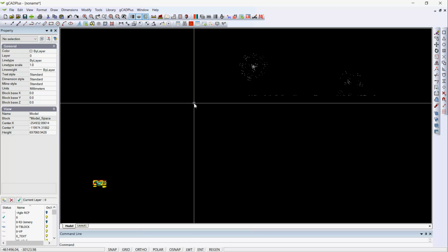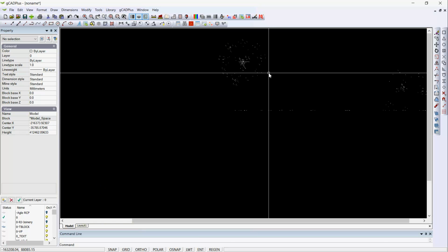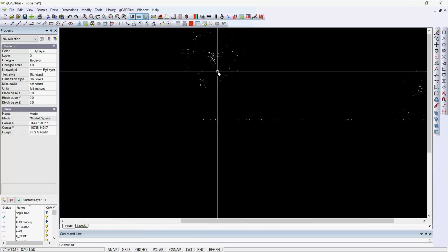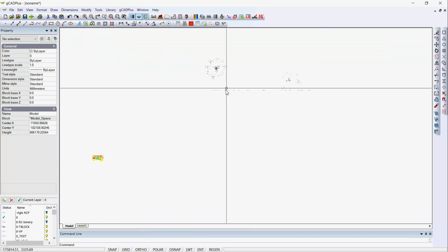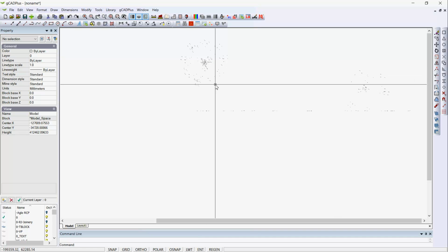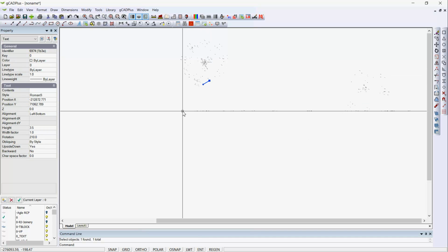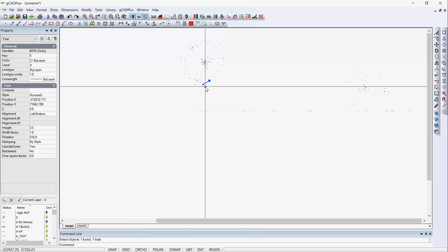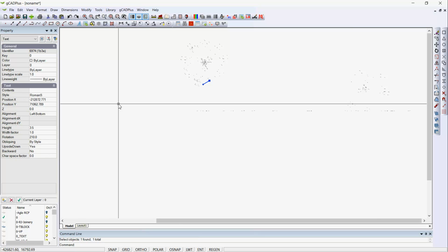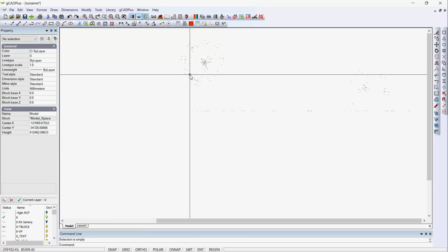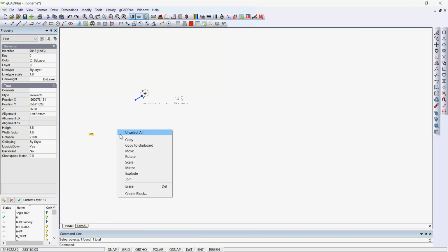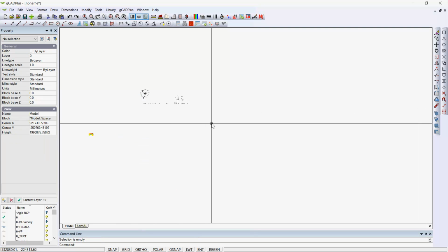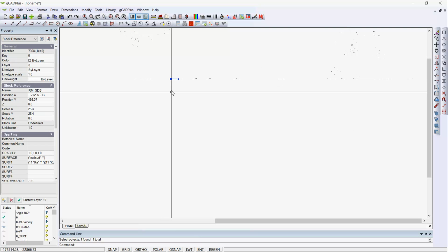Whoa! And immediately you can see lots of, we can call them interesting observations, but let me put the view to background color white, and way over here are a whole lot of entities. Let's just select one of them at random, and it's a piece of text way outside, and not only that, it's a text with empty contents. Unselect all, jump in here, more text which is empty. So I can unselect all. Let's get rid of that text because surely it can't be of any use.